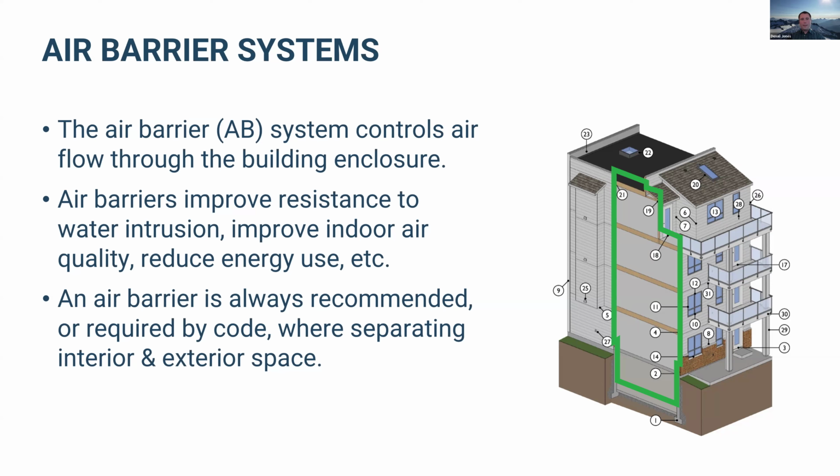But this is really an essential part of a high performing building. It's the most effective way to manage rainwater. It's going to increase a building's durability and resilience. It allows you the opportunity to add more insulation and make the building more energy efficient. We're seeing a lot of really cool deep energy retrofit projects that include adding a rain screen and insulation to an existing building.